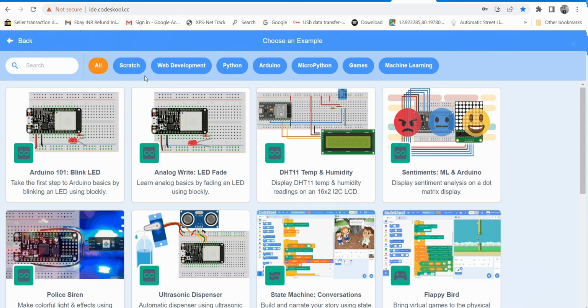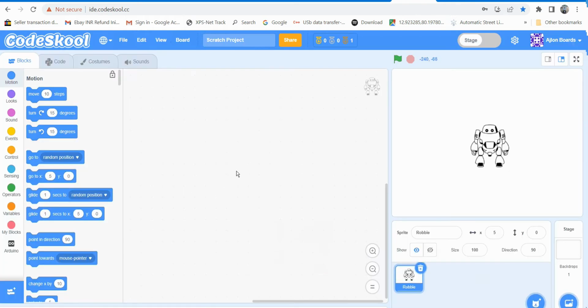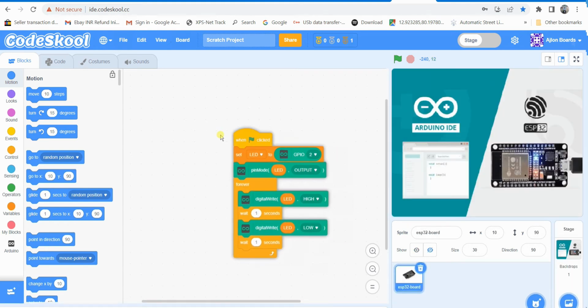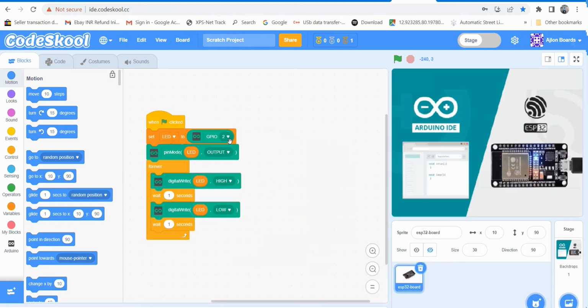You can also use the same code. You can click this button, and you can see the response in the board. The board light is on GPIO pin number 2 in the board, which is D2, and the D2 pin is defined as LED pin by default. Otherwise you can name it as number 2. So this loop keeps on looping once you click this button.